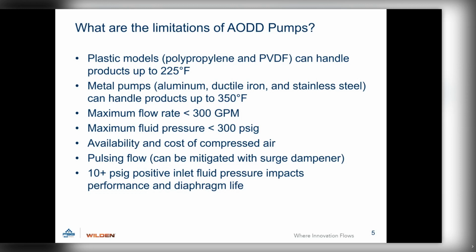So availability and cost of compressed air is slightly higher than running just an electrically driven pump. However, in many instances, you can't have electricity and water mixed together. This is where the diaphragm pumps really excel in those areas.